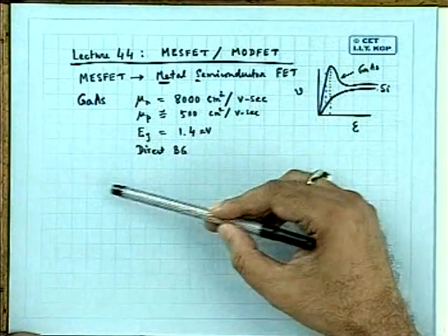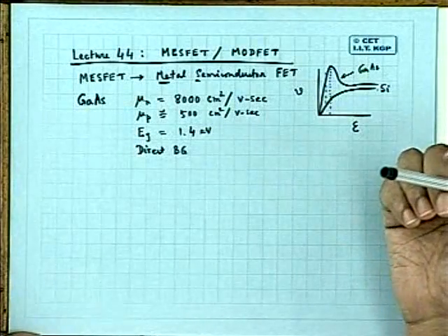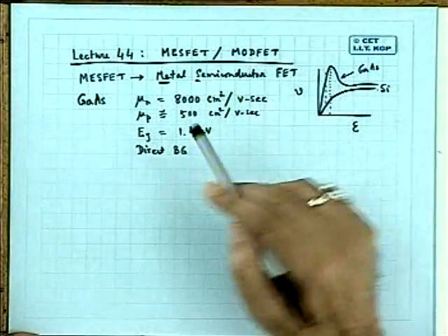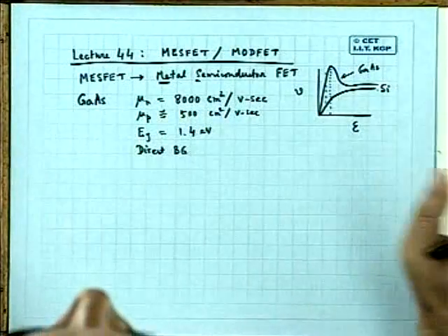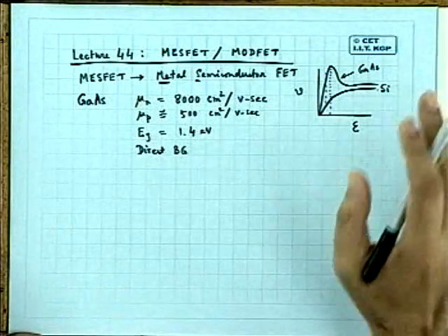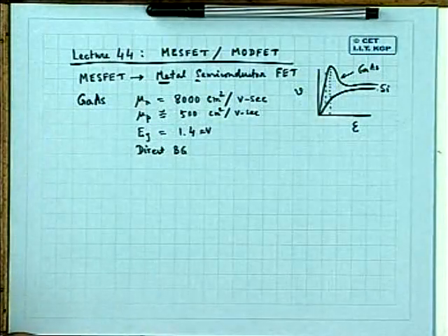Gallium arsenide started facing challenge again from silicon once the MOSFET came. And MOSFET coming meant entire ICs became LSI, VLSI and all this, which bipolar could not. But with gallium arsenide, they found there is a problem. It is very difficult to make gallium arsenide MOSFETs.